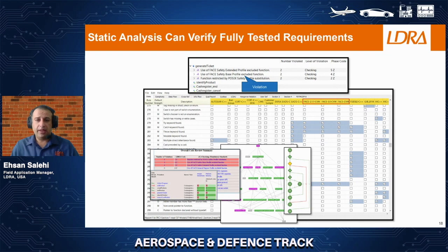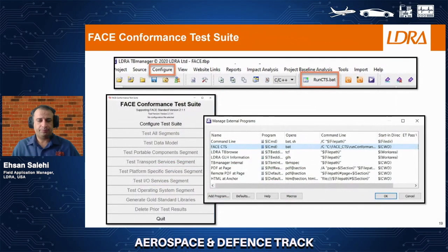So in order to create a test and using the code inspections, the user can simply go ahead and use the LDRA TBvision static analysis to see the process results. One example is that it checks for the adherence of specific sections of the POSIX API, ensuring that the UOC function signatures are syntactically correct, enforcing the proper use of certain language constructs.